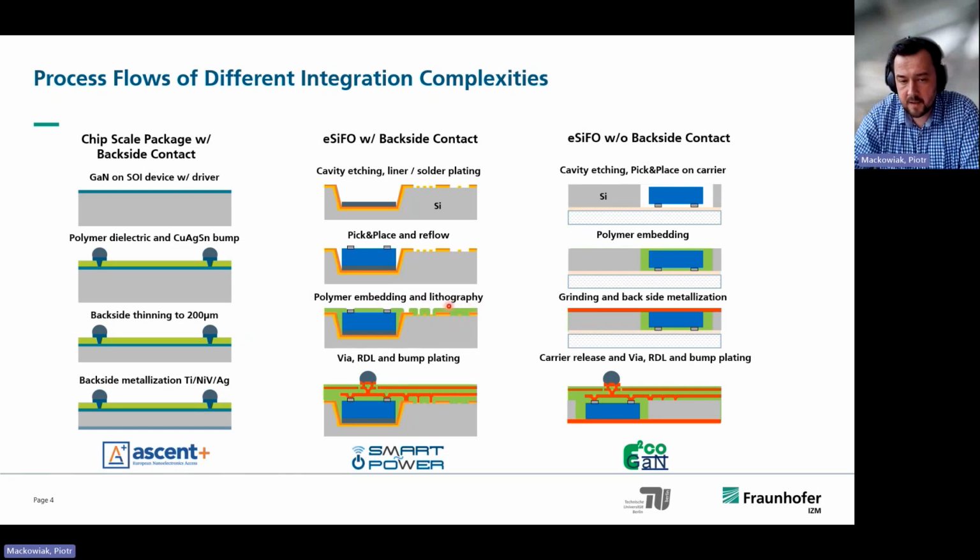And with this we were able to polymer embed this chip. So we applied the polymer and filled the cavity, and within had an almost flush mount surface where we then could continue with our redistribution layers and access the chip from the front side. And a final metallization with a bump would enable us to have some flip chip assembly later on.